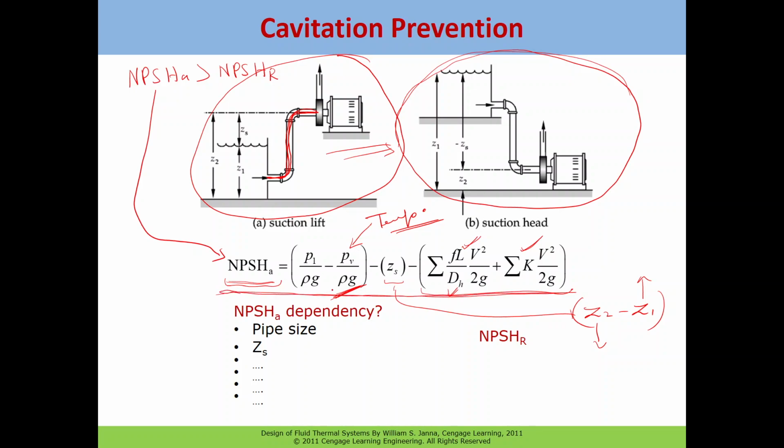You have to understand this equation because you need to calculate the net positive suction head for your systems in several configurations, whenever you solve any design problem, whether you are designing a housing network, a greenhouse, a mall, or an office network, whatever it is. So this is about cavitation, and in the next lecture we will do one example related to the cavitation phenomenon, and you will understand more, inshallah.